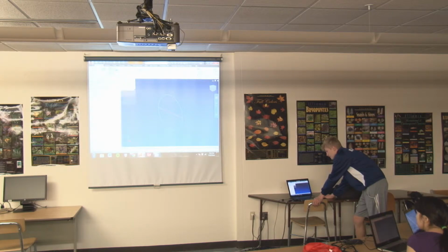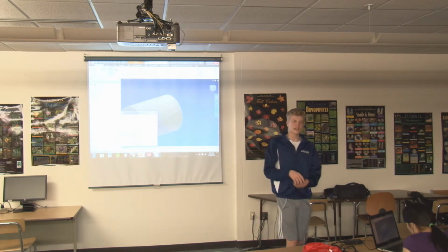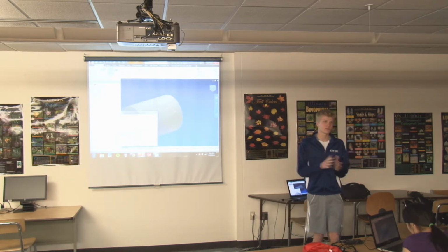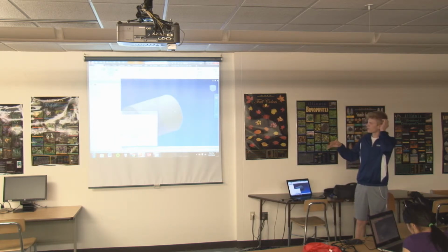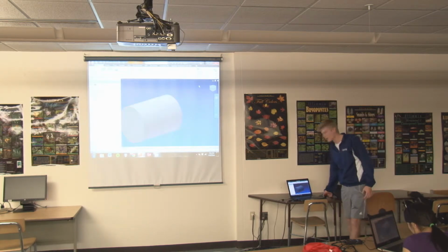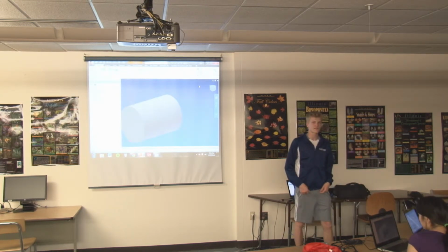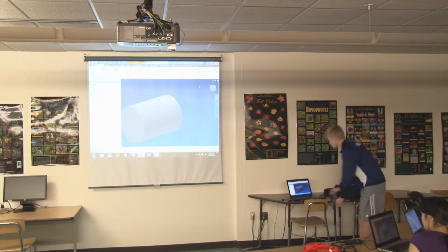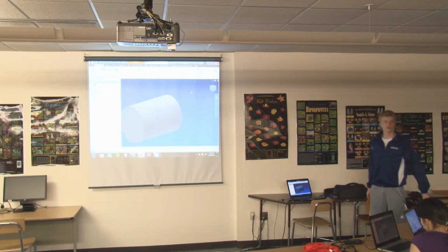What Extrude does is if you click on any two-dimensional sketch, such as the only one that exists here, the circle, it'll take it and it'll stretch it out to however long you set it to. Right now it's set to 1 inch. So if you hit enter, you can create that. There are a number of other tools associated with that that I'll go into depth in my other tutorials, but that's a basic extrusion.